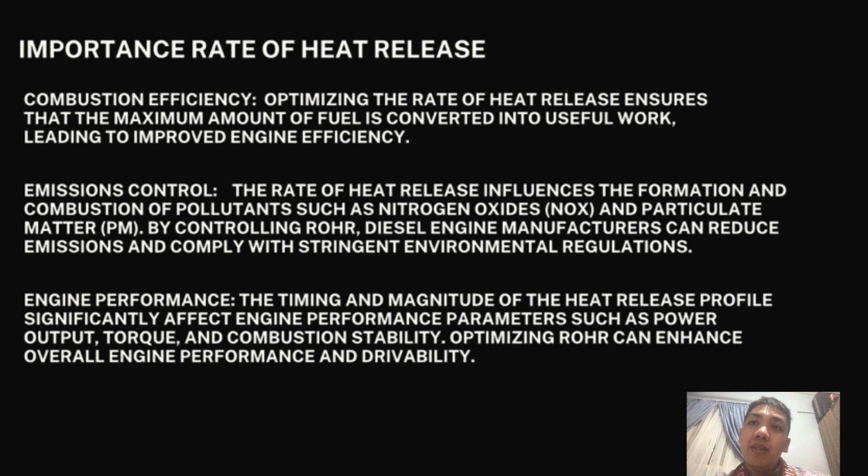Why is this very important to know? Because we can optimize the rate of heat release to ensure that the maximum amount of fuel is converted into useful work, leading to improved engine efficiency. Another is emission control. The rate of heat release influences the formation and combustion of pollutants such as nitrogen oxide, NOx, and particulate matter, PM. By controlling ROHR, diesel engine manufacturers can reduce the emissions and comply with strict environmental regulations.